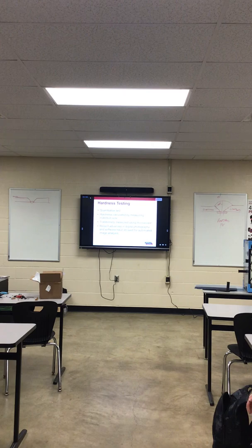It's a quantitative test. Hardness calculated by measuring indentation size. So going back to this, we have a conical shaped tip and a diamond shaped tip. Judging by those two tests, how far it indents based on how much pressure and how long they leave it there, they're able to measure that and tell them, okay, this has this Rockwell setting.